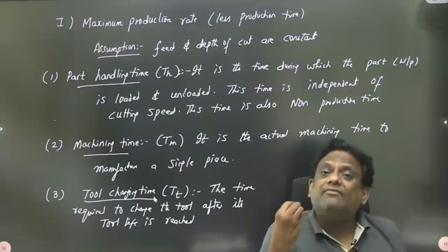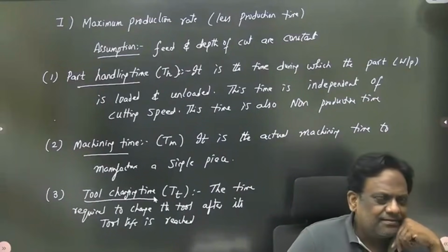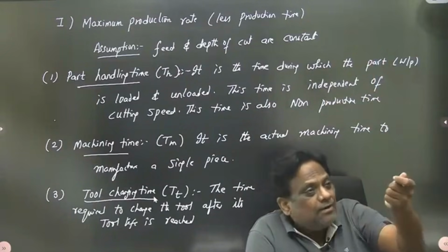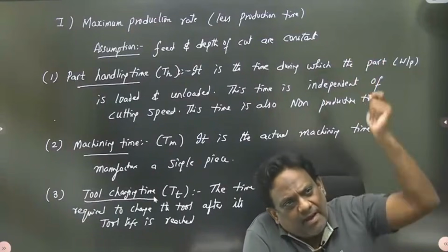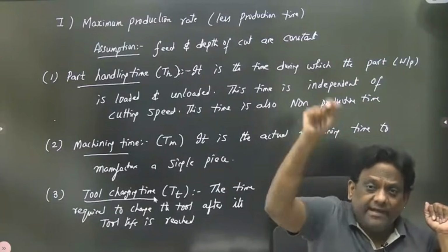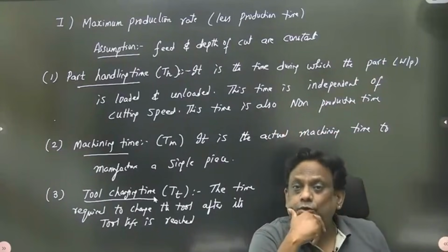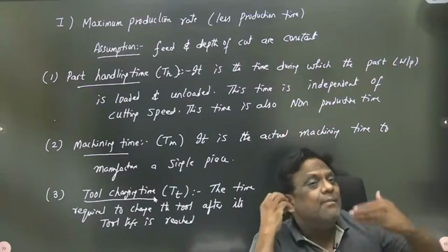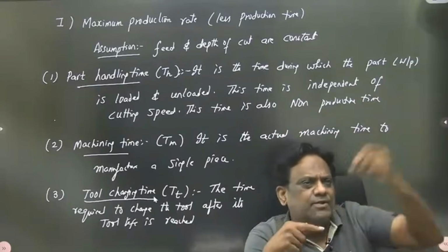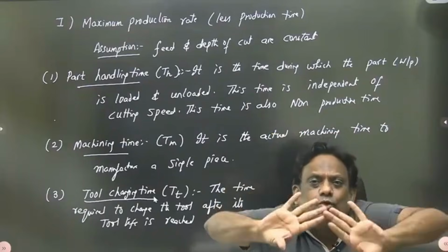नहीं, maybe after 20 hits. Let us say the 19th hit is over. So now exactly at the 20th hit, एक बार 20 बार मारने के बाद वो टूट गया. So can I say only the 20th hit is responsible for breaking that workpiece? No, na. So as I am cutting, first workpiece I have manufactured, second workpiece over, third workpiece over, fourth, ऐसा करने के बाद, let us say in the 13th workpiece the tool got damaged.